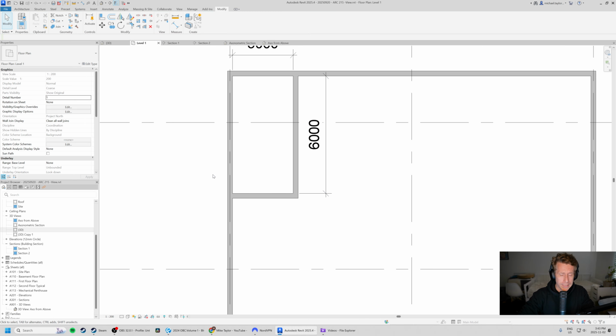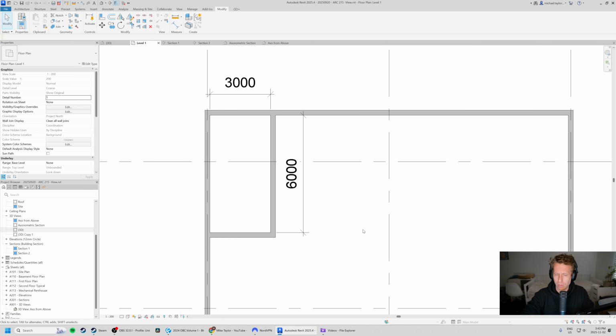In the olden days, you would have to do all these calculations on your own in an office with a calculator or by hand, whatever you prefer. I used to literally sit there and say, okay, how high is the space from one level to the next level, and divide by some number. Then you'd figure out how many risers you had, which is the elevation, so up as we come up the stairs. And then you need to figure out how many treads you have, so that's how many treads in plan. Revit automates all of these things for us.